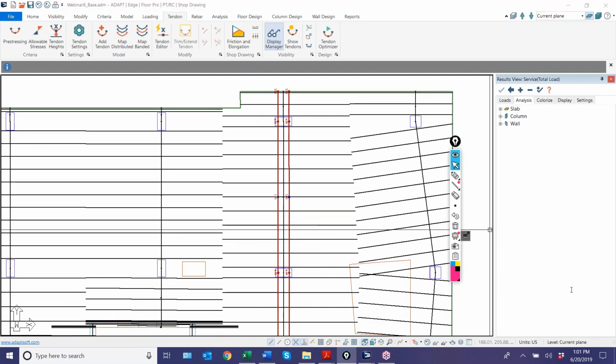There's another question. Yes, Marcos. Usually the more tendons you have, like if you model and distribute all the cables, you're going to get an improvement in the accuracy for deflection. Unless the deflection is really sensitive and you're trying to get the most accurate representations so that you can justify the amount of displacement relative to a criteria, then you may have to transition to multiple cables versus lumping them like we're doing here.